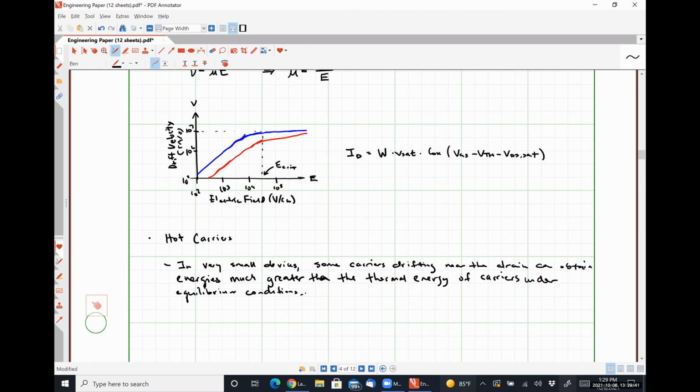As soon as that oxide starts getting doped, it starts becoming electrically conductive. And an electrically conductive path means that some portion of our drain current gets steered off and is able to flow into or out of the gate. So we are losing the control that we have over the device's operation, right? So that's what hot carriers do.